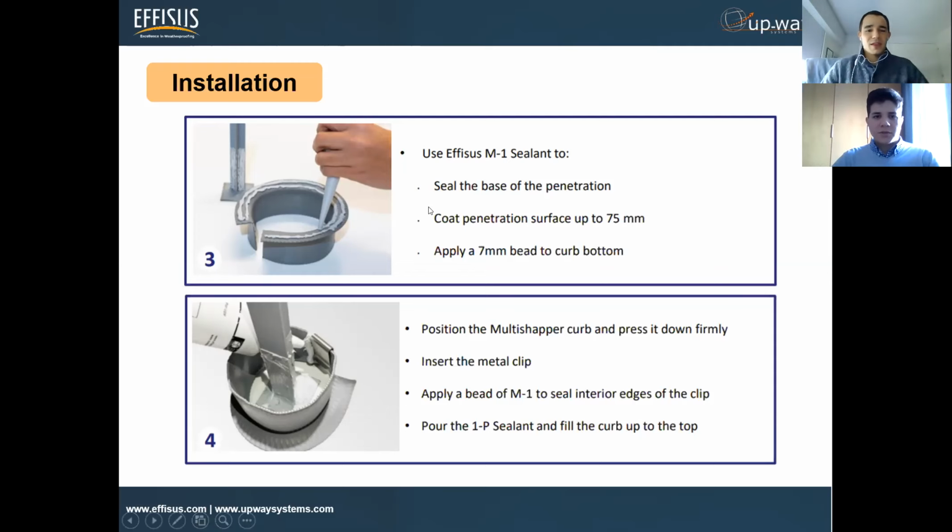Absolutely. It retains its characteristics, and I forgot to mention it will cure over time. In the beginning, it's very flexible. What we always recommend is that this cannot be installed during rain. It must be good weather conditions just for the application itself. But after 30 minutes to 1 hour, it can be completely exposed, no doubt.